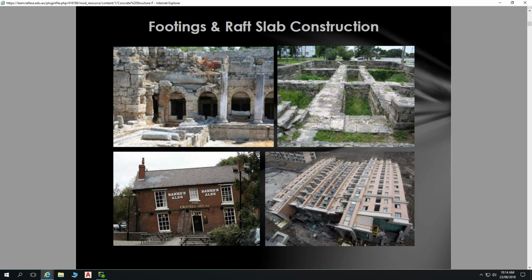Once your concrete is cast, you pump a non-shrink grout through those conduits to bind with your steel. Hence, your steel is bound to the non-shrink grout, which is bound to the conduits, which is bound to your slab. Then you release the pressure on those. So that's post-tensioning. Pre-tension happens in the factory, post-tension you can do on site.